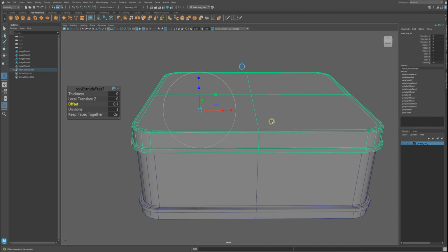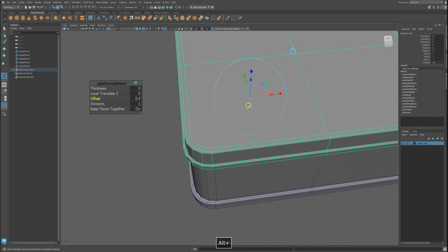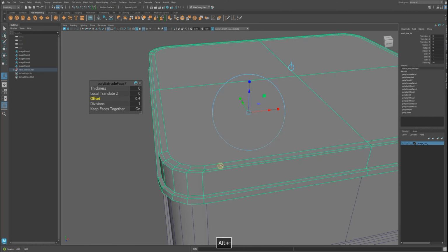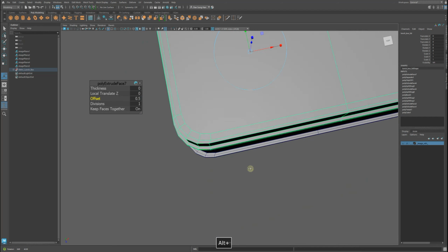Alright, so here we are. And like I said, you select your object, click that, and your menu pops up. So I'm gonna think about starting from here, up to this much, where I want that footprint spacing. So instead of offset 0.5, I'll make it 0.1.